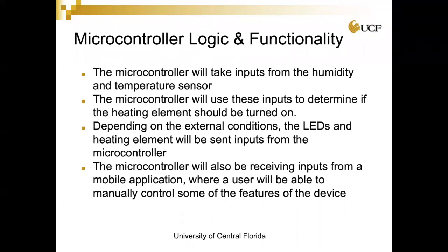Microcontroller logic and functionality. The microcontroller will take inputs from the humidity and temperature sensors and use these inputs to determine if the heating element should be turned on. When the heating element is turned on, the LEDs will change color or turn on depending on the mode and setting. Depending on external conditions, the LEDs and heating element will be sent inputs from the microcontroller.